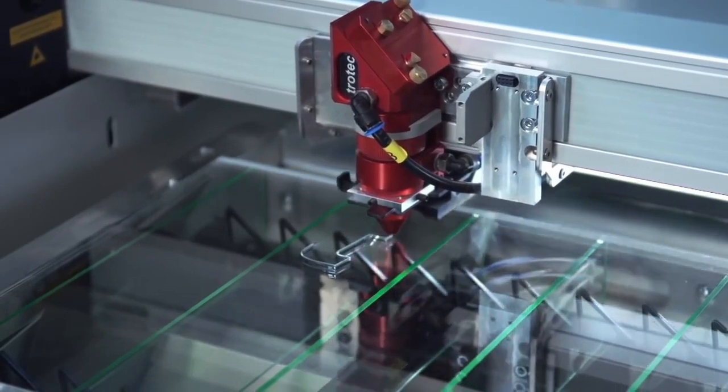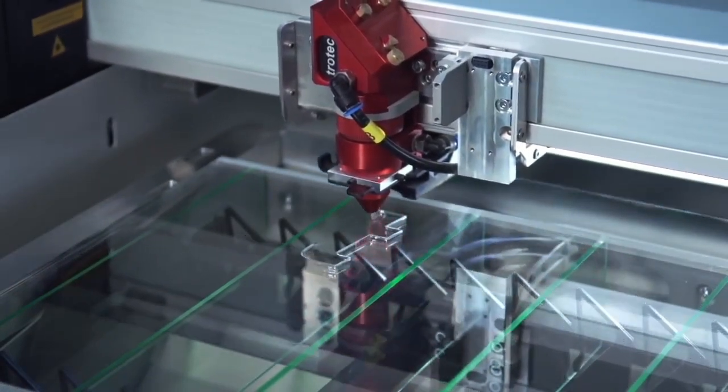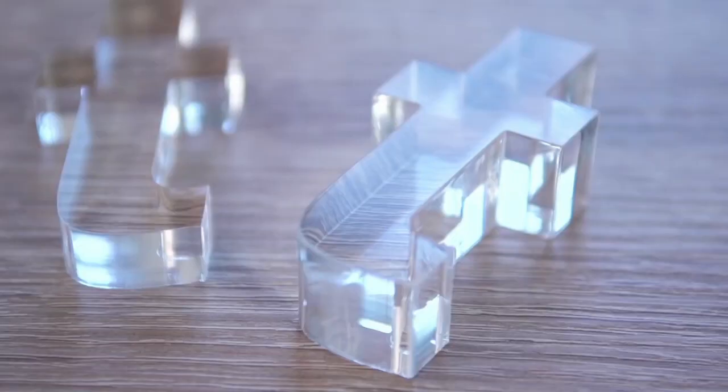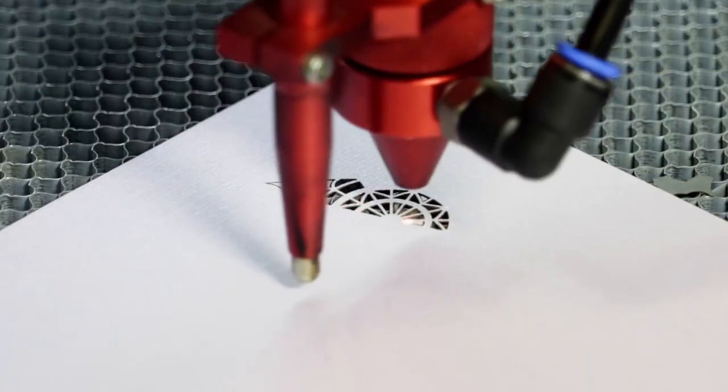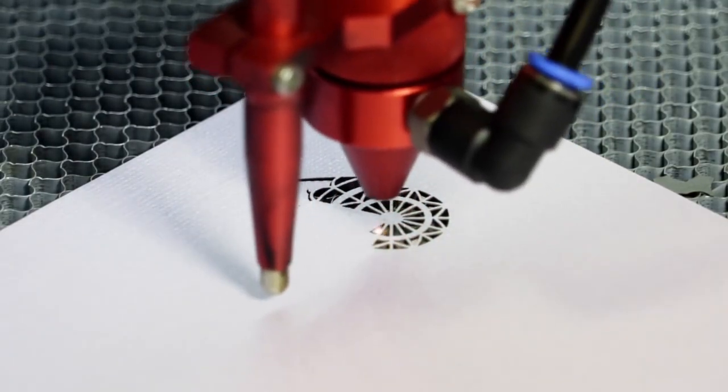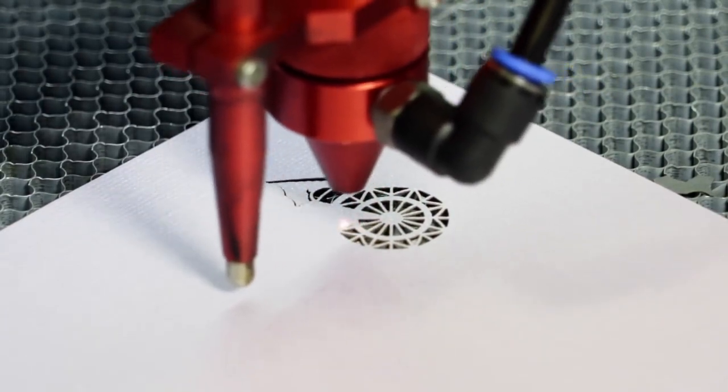For cutting material like wood, glass, plastic, etc., which absorb most of the radiations, inert gases like nitrogen or argon can be used in the place of oxygen for laser cutting. A low energy 100 watt CO2 laser is used to cut papers and create various designs on it.